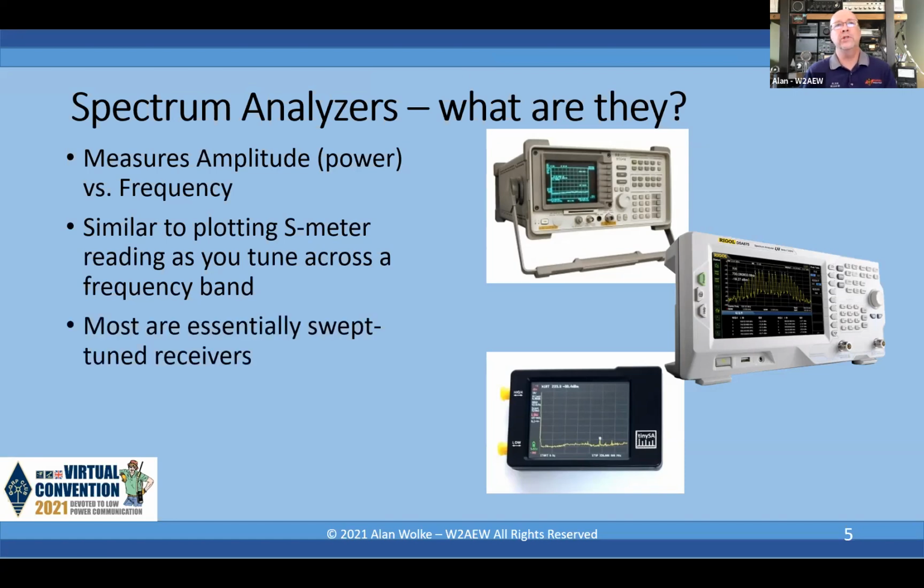In a sense, you could almost think of them as a swept-tuned receiver. In fact, the architecture of most, especially the old school spectrum analyzers like these guys here, is really nothing more than a very sophisticated swept-tuned AM receiver. That's what it comes down to.